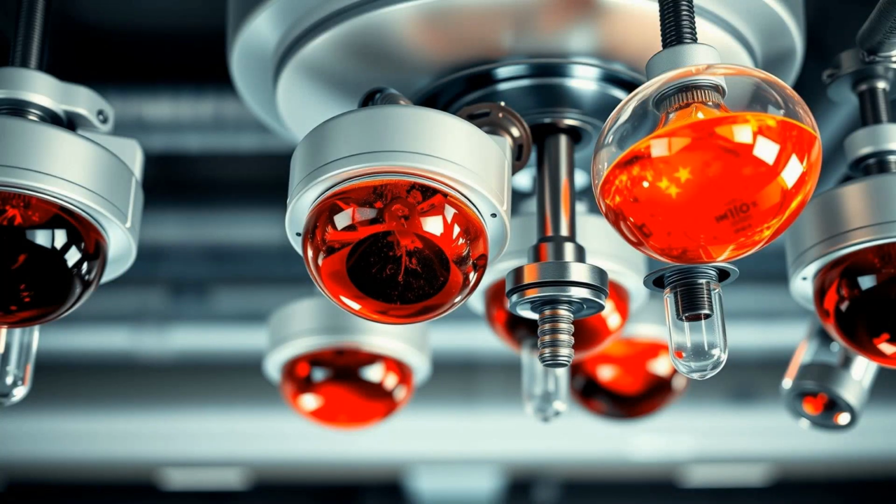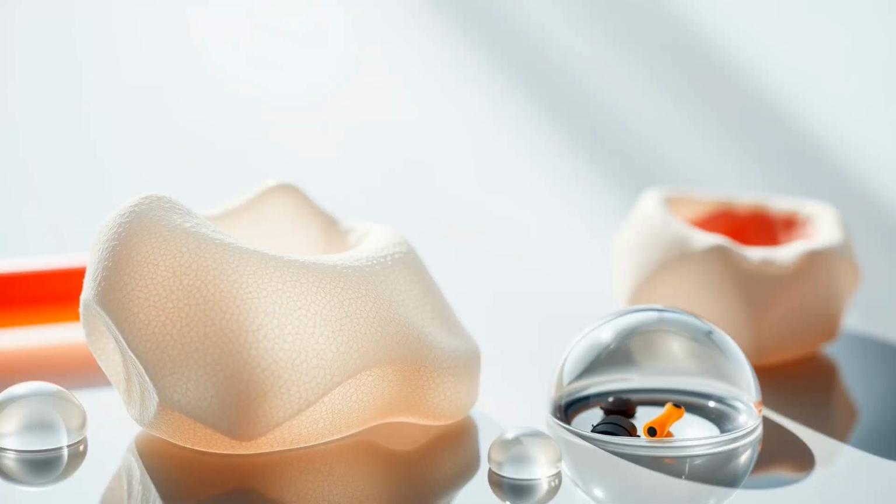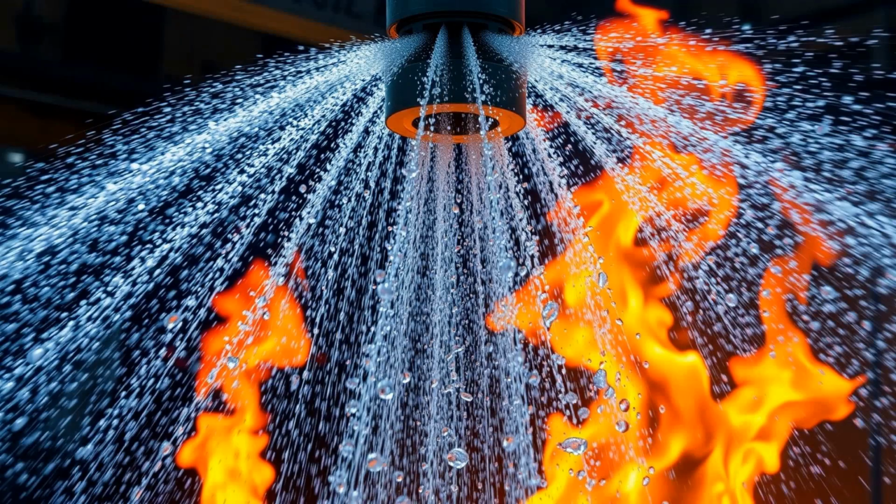Each sprinkler head is equipped with a heat-sensitive element, either a glass bulb filled with a liquid that expands when heated or a metal fusible link that melts at a specified temperature. These elements are calibrated to burst or melt at a preset temperature, commonly 68 degrees Celsius (155 degrees Fahrenheit), which is typical for offices and residential buildings. Once this threshold is reached due to the buildup of heat from a fire, the sprinkler activates, allowing pressurized water to flow directly onto the fire.